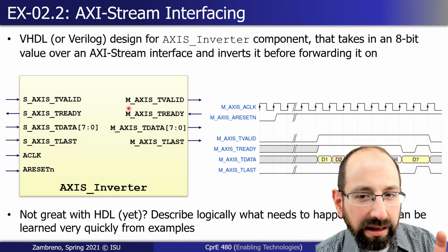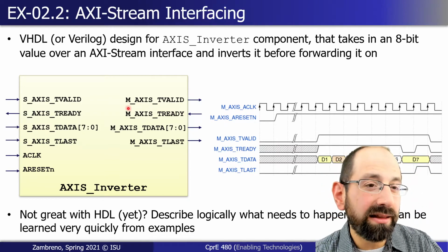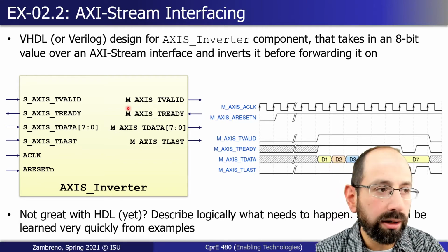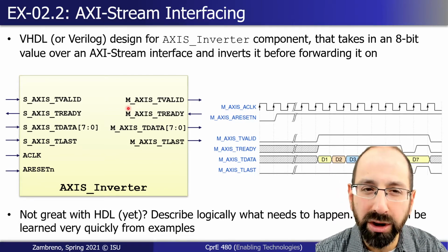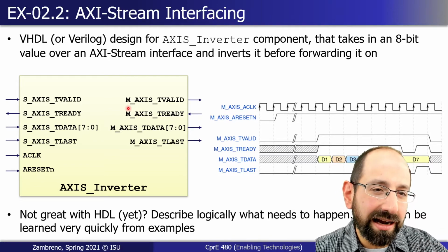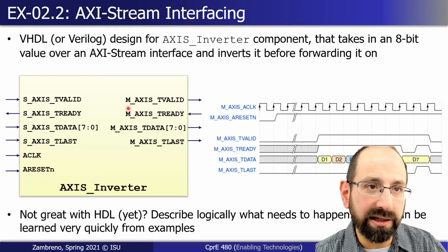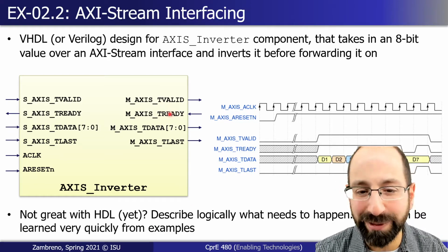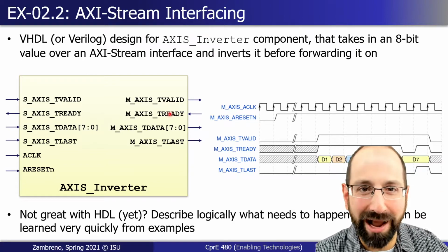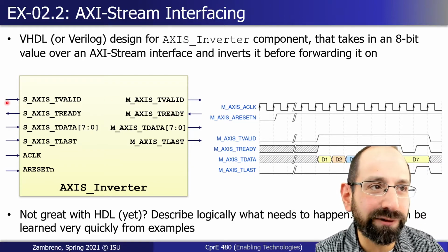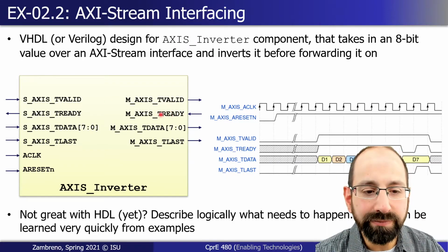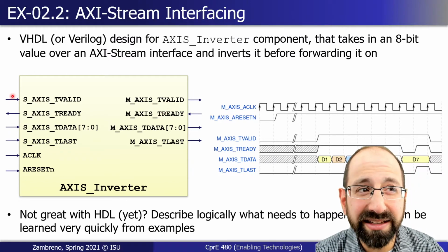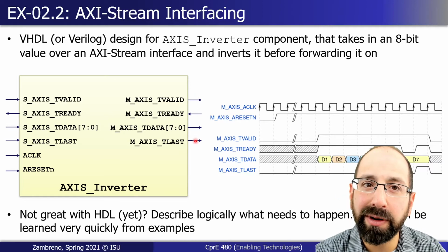And so you may start to get that backwards if you're not careful, right? This is an IP core that's passing data through. Your viewport core is also passing data through. So it's both, right? For these point-to-point connections, it's both a receiver, it's waiting to get data, and it's also a sender. It's going to be sending data downstream. I sometimes get upstream and downstream backwards, but it's good enough for our purposes. Data is flowing downstream. So it's both. And so you do have to keep track of what are the signals that are my input ports and what are the signals that are my output ports.